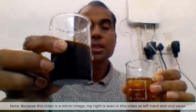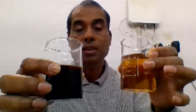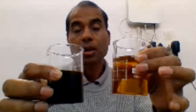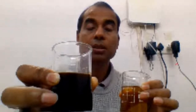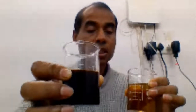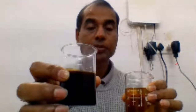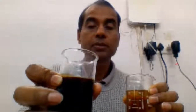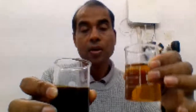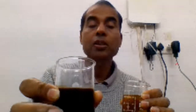This is the oil you see in the workshops where they do the oil change. So this is a new engine oil for a car, and this is the oil which has been used for something like 3 months in a normal application. Within 3 months you can see how the color has changed. Why has the color changed? Impurities present in this oil. What kind of impurities? Wear debris. And due to the high temperature, there is degradation of the polymer in the oil, and wear debris. If you do the debris analysis, you will find a lot of metallic particles here.